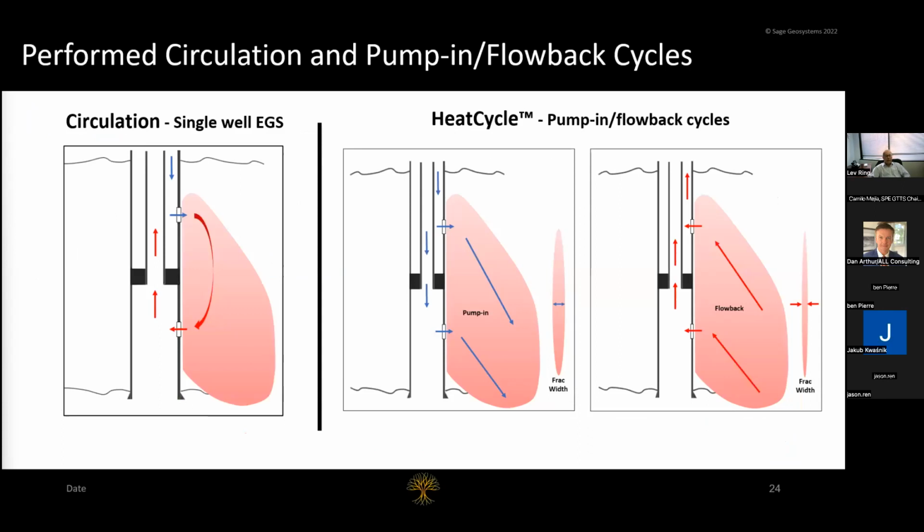So we created this fracture, and we were using 20, 21 pounds per gallon fracking fluid, which was actually drilling mud. And we started to circulate. But of course, to open and circulate, as we discussed before, due to the friction, we're losing more than 30% of the fluid into the formation because we could not keep our pressure below fracture propagation.